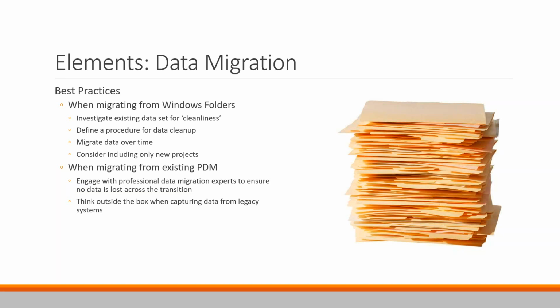And this is something we do as part of our implementations: we take a look at the information and we try to come up with a step-by-step process for how to take what is broken data sitting in a network folder, get it cleaned up and organized so it can go into Vault the way you would like. That usually is, step 1, pack and go to the workspace. Step 2, reorganize the files into the correct folder structure. Step 3, open up the Inventor assembly or drawings and make sure everything resolves. Check it into Vault, maybe do a rename to make things unique, and then repeat.